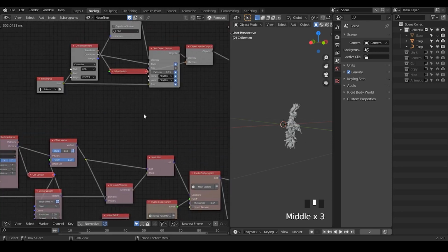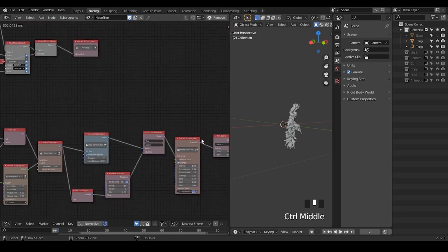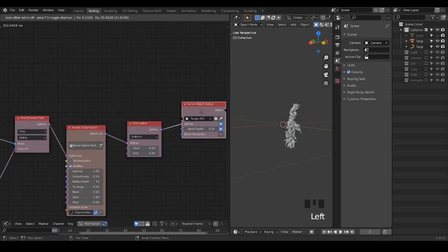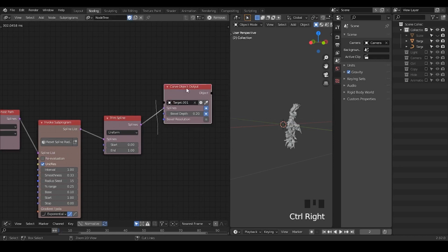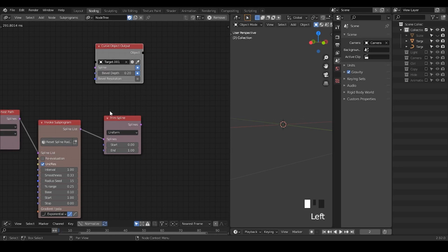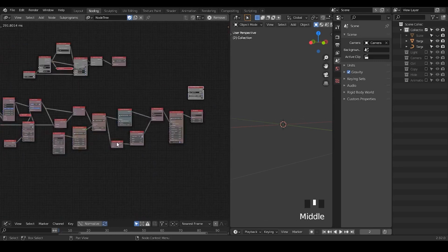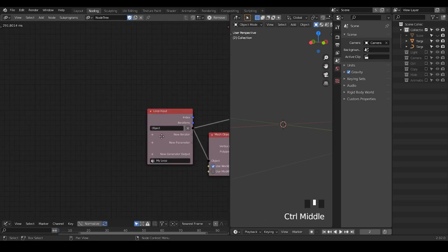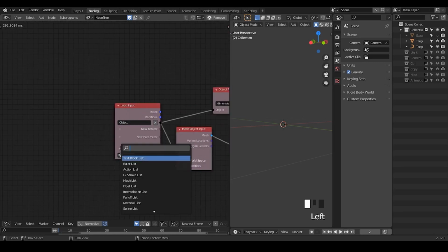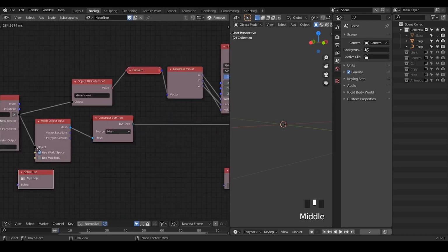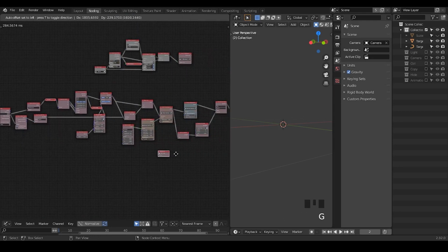One reason is that we are generating multiple splines within the same loop, but we are writing to the same object, so it keeps overwriting the data. So what we do is not generate this curve object inside the loop. You can, but you need to use slightly different methods later. Just to keep things simple, I'm going to go to outputs, hit this plus icon, and take the spline list. Finally, we're going to output this spline list.